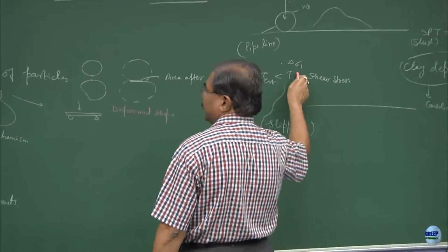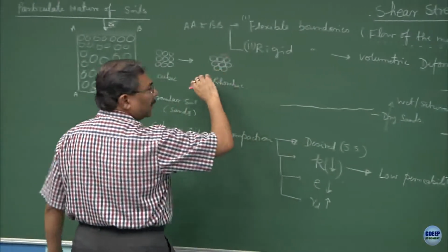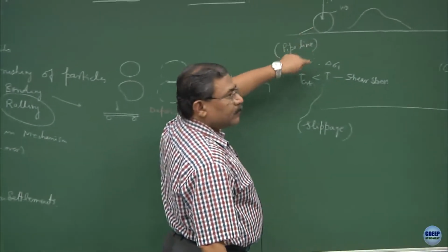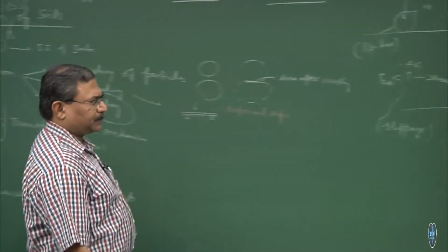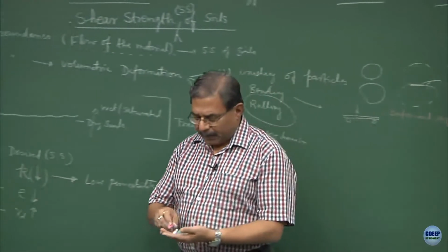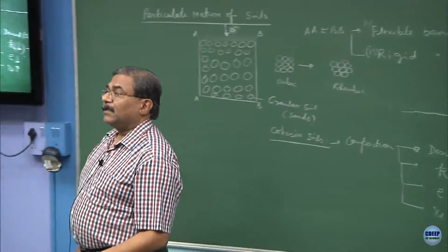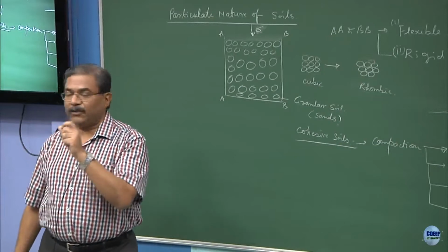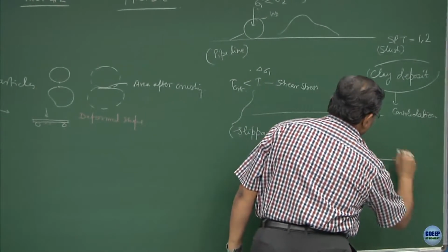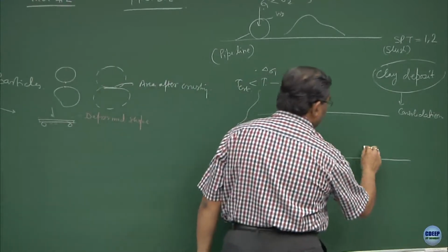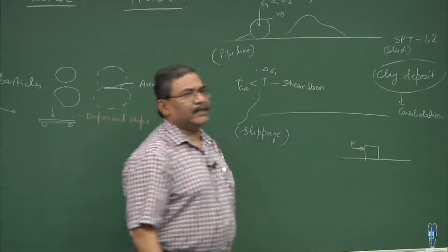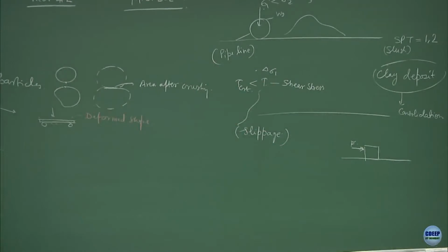So, because of the development of shear stress in granular material, there will be a rolling over of the grains, you were right. When we are talking about the cohesive soils, rolling is not possible. What is going to happen? The slippage is going to occur, clear? What is the slippage? In engineering mechanics, you have done these type of problems. So, it is an extended example of the case which you have already studied in engineering mechanics. Suppose I give you a situation like there is a horizontal plane and there is a block lying over here, and then if I apply a force, you find out the kinetics and kinematics of the system, that you can do very easily, clear.